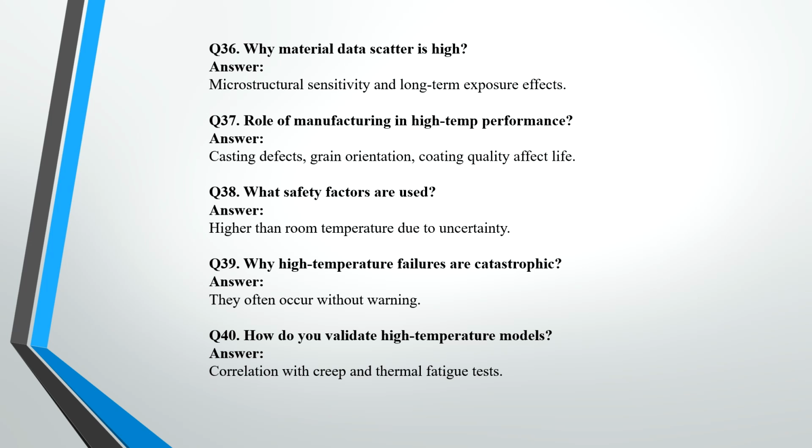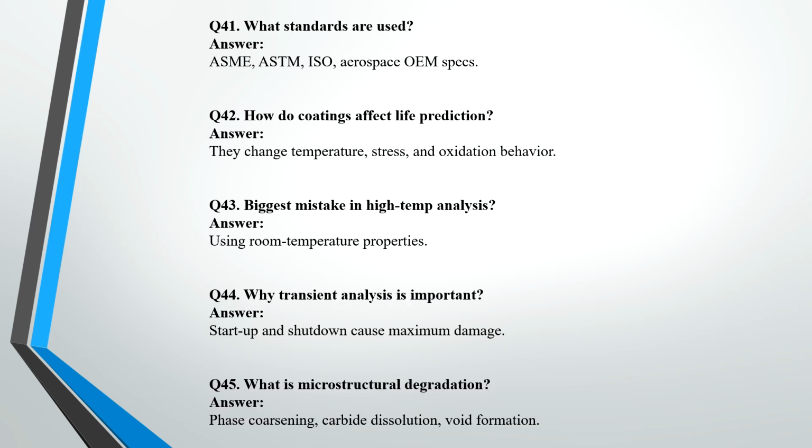Why are high temperature failures catastrophic? They often occur without warnings. How do you validate high temperature models? Based on the correlation with creep and thermal fatigue tests. So there are some standards we use. What standards are we using? We are using ASME standard, ASTM, ISO, aerospace, OEM specifications. These are some of the standards we follow while designing high temperature materials.